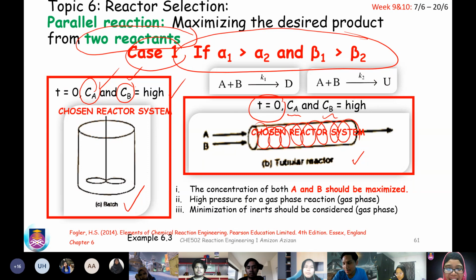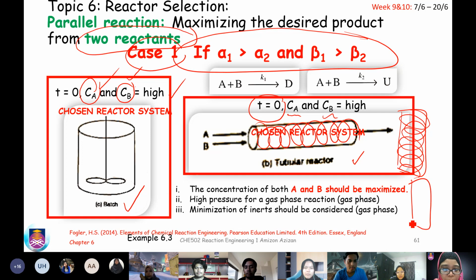And again, tubular can also be vertical. Tubular is still tubular because of its shape. For vertical, normally we have that when we put in our packing. We can also assume it behaves like a plug flow reactor. If it flows out straight like that, it can also be assumed that way. Right, very good question, Akasha.